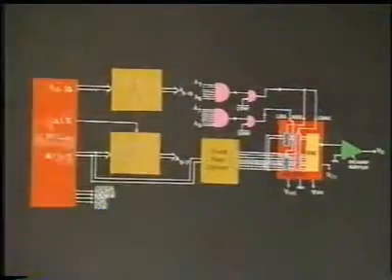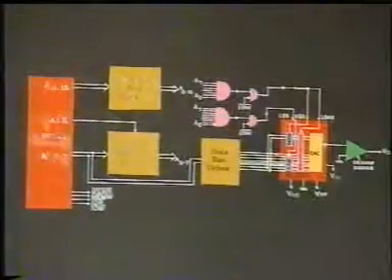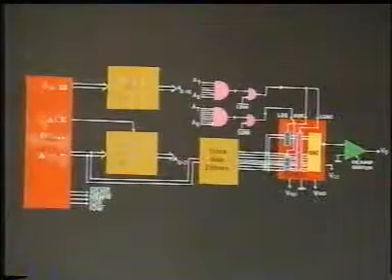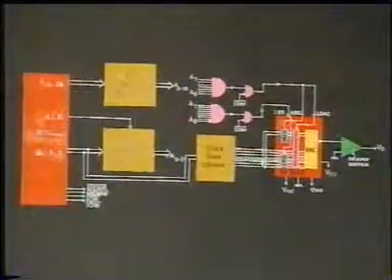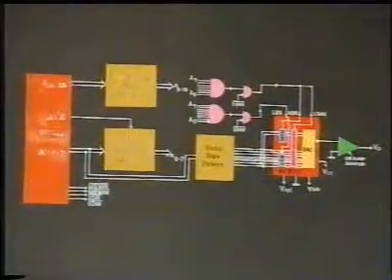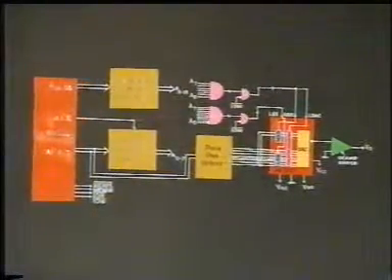Now let's take the interfacing of a D to A converter with a higher word size, say up to 16 bits. In this case, the technique remains the same. The only thing is that we have to have 2 ports. Say there is another port.